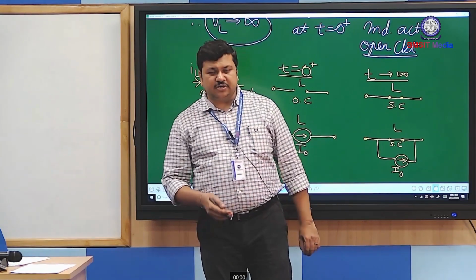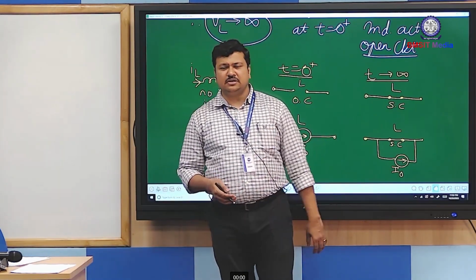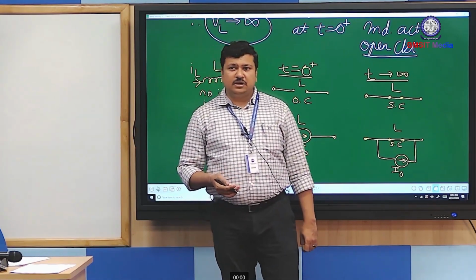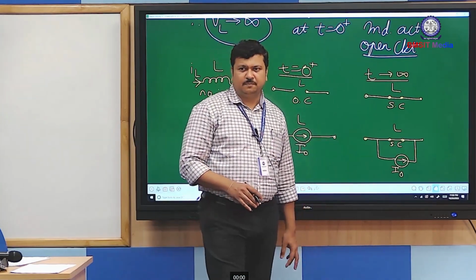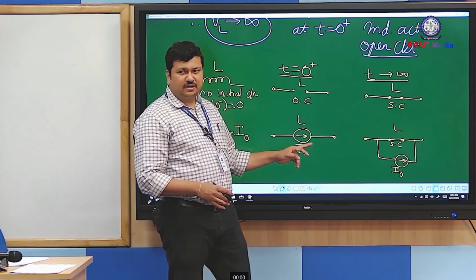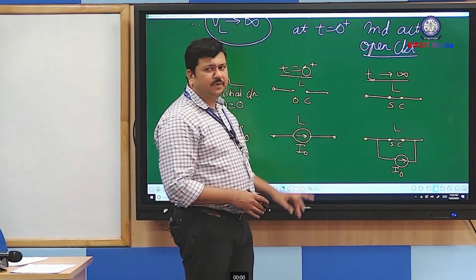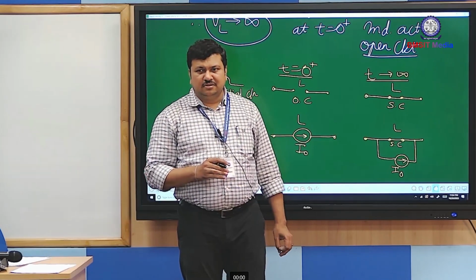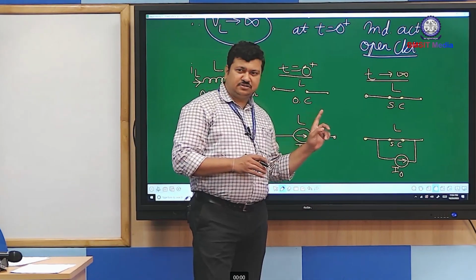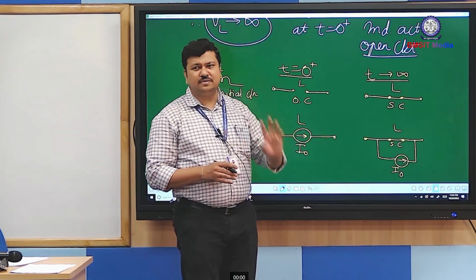In the previous subject, fundamentals of electrical science or basic electrical engineering, we have seen how the inductor is behaving for AC, and all those analyses are steady state analysis. But this is how the inductor behaves with respect to time. So we have one more energy storage element, capacitor. We shall see, and what happens with inductor, exactly opposite happens with capacitor. If here current is not changing instantaneously, in capacitor voltage will not change instantaneously.